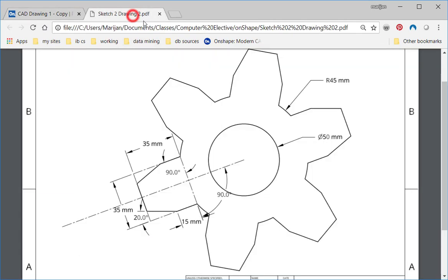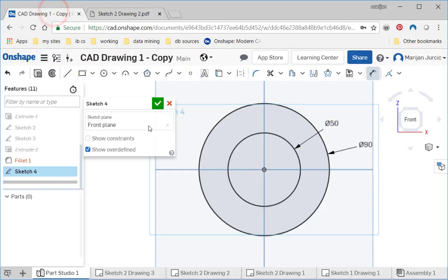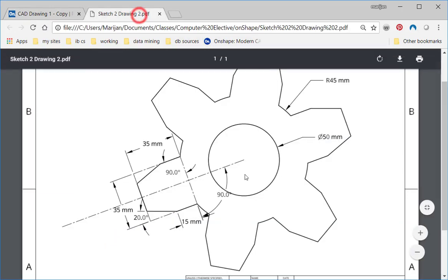Next thing is I'm looking at this line. This line looks like a symmetrical line for all these little pieces, right? So this looks like it'll be a good line to make, and then try to make these pieces around it. So I'm going to make that a construction line, and it doesn't matter where, anywhere out like this. Escape to get out. Okay, what's next?